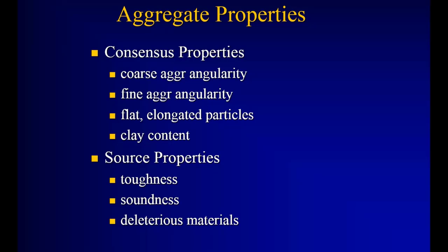So all those probably look familiar if you've worked for a while or even in the Marshall world prior to Superpave in North Dakota. Well, coarse aggregate angularity is just fractured face. And of course, coarse aggregate stands for all the +4 material in our aggregate blend. +4 sieve, meaning a number 4 sieve is, if you look at the mesh in the sieve, 4 openings per lineal inch.